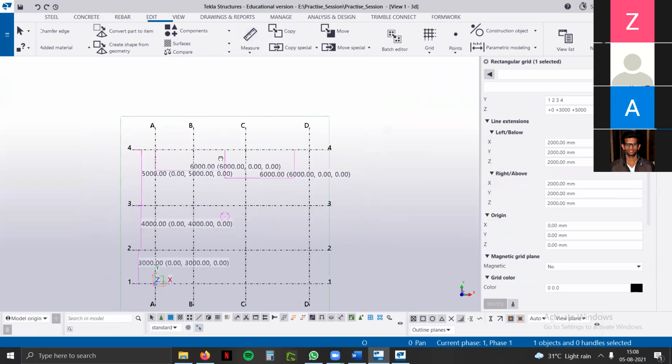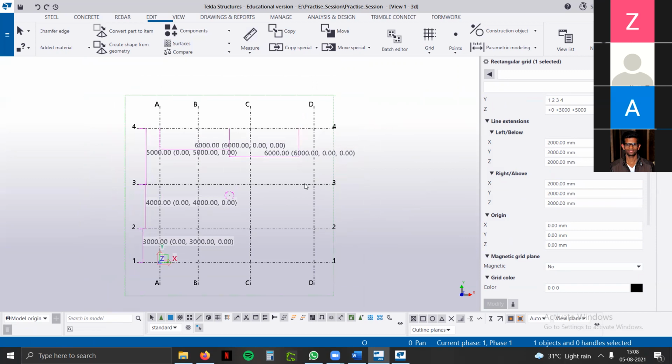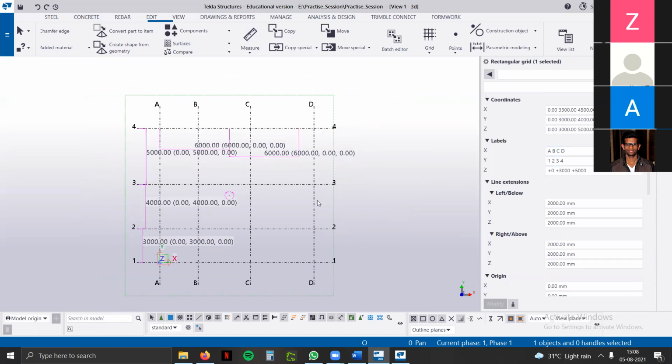Now we have talked about the x and y axis. What if we want to add planes in that? We want to have a different set of levels, because a building will obviously have some stories, multi-story, whether it is G plus 1, 2, 3, any of it. If there is a basement, then we also provide it. So I'll talk about ground and plus 2, 3 coordinates. We'll add some planes over there. I'll take the height of the building as 3,000 first, and